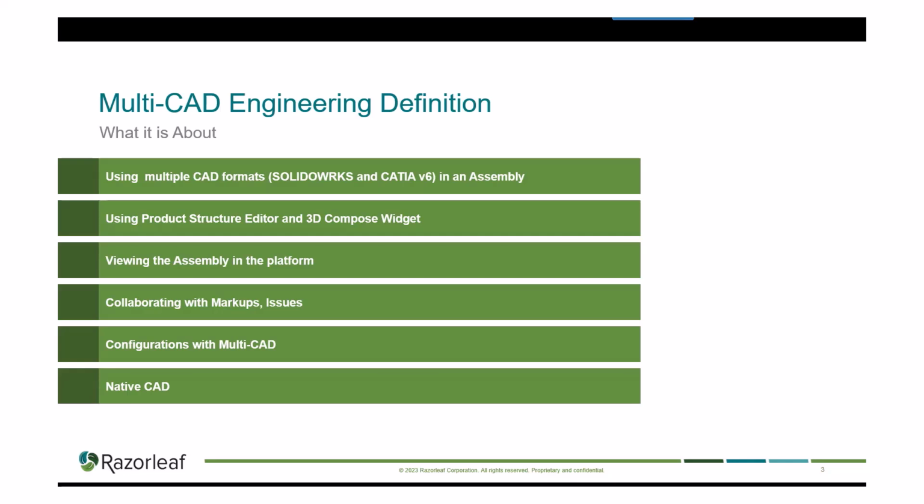Things like insert components into the assembly and even manipulate the positioning, things like that. You have positioning like concentric or point or tangent and things like that. So you can do a fairly good job of placing components in an assembly just using the widgets without doing the native app. Now, it doesn't mean that you don't use the native app to do or finalize connections or things like that, but you can still build an assembly.